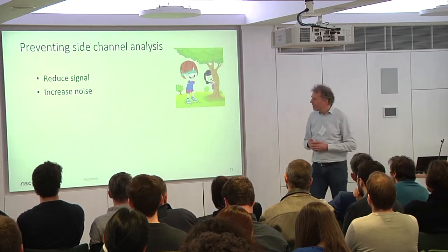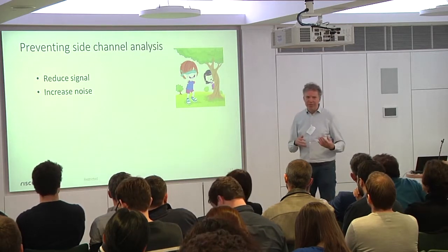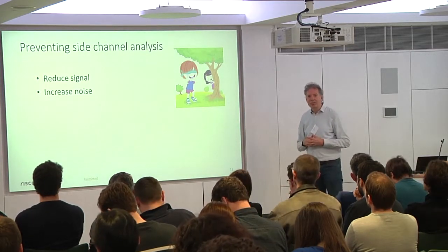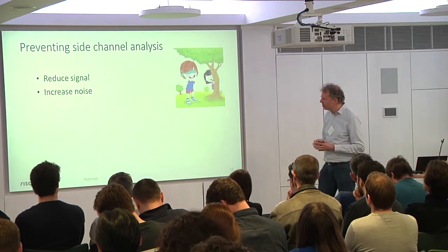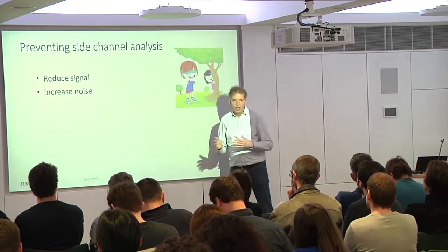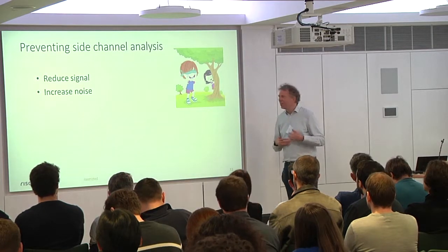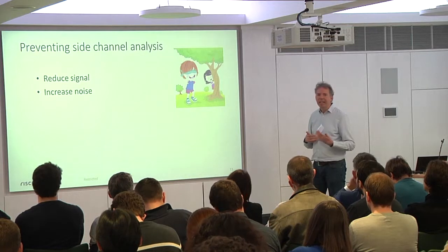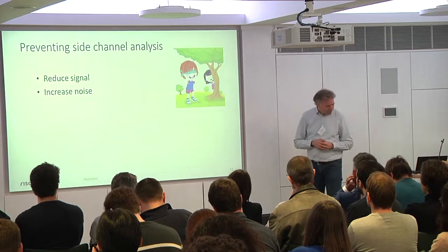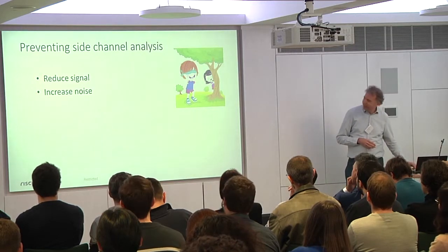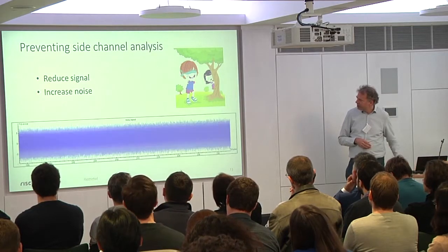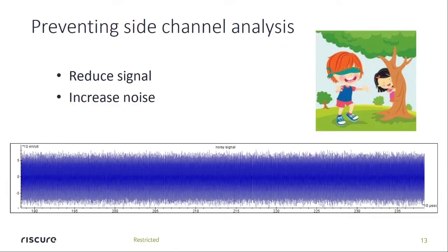It could also be parallel cores. So if an SoC would include several cores all running their own processes, it would generate a lot of noise. If the clock on a chip would be free running and not quartz driven, it would vary a lot over time. That creates timing noise. So nowadays, when we look at chips that have some level of protection against side channel attacks, we would see something like this.